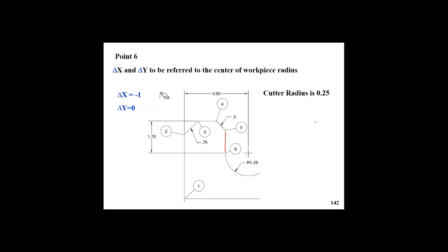In that case, instead of referring the cutter location to the edge of the workpiece, we refer to the center of curvature. So if this is a curvature and this is the center of curvature, we have to refer the cutter location, if this is our cutter. It is better if we locate the center of the cutter at the center of curvature. So that will be dx, instead of our previous treatment.